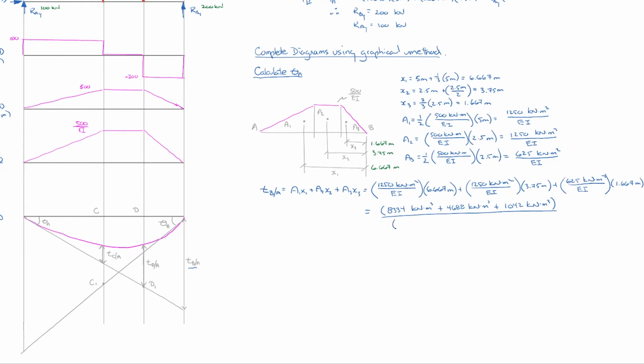So I am going to plug the numbers in here. We have 200,000 MPa, or multiply that by 10 to the third to put it into compatible units of kilonewtons per meter squared. And I, which is our 1.20, and in this case we're going to multiply it by 10 to the negative 3 to make it meters to the fourth instead of millimeters to the fourth.